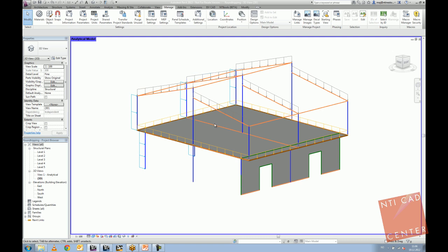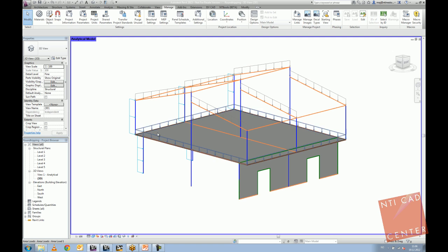What would be really useful is a little more control over what is the start and end of the element, because these things might be important when you go to Robot for analysis, or when you apply loads, for example when you say that the load should be located at the start of the element.